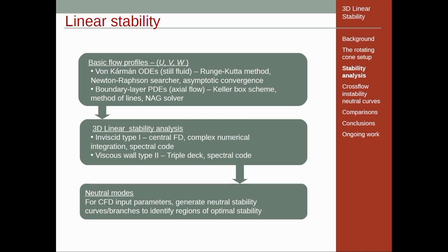So we already know a little bit about how to attack this, and it turns out that when we do the asymptotics, there are two modes in particular that we can see. One of them occurs as a result of essentially a Rayleigh equation in a layer that's, I think, 1 over root Reynolds number in size, and then another layer that's closer to the wall.